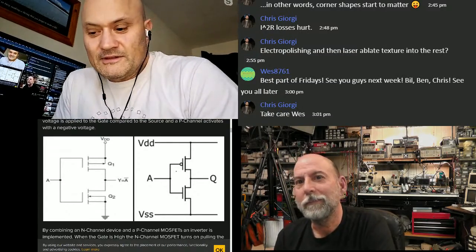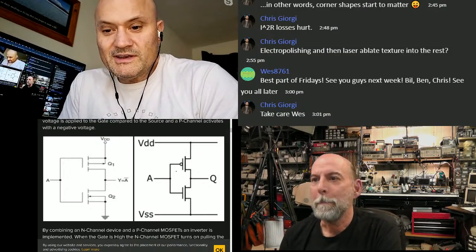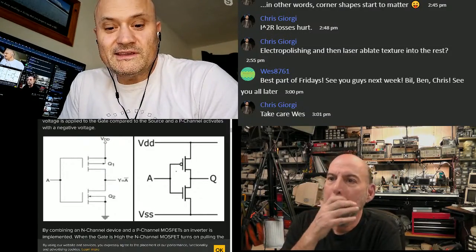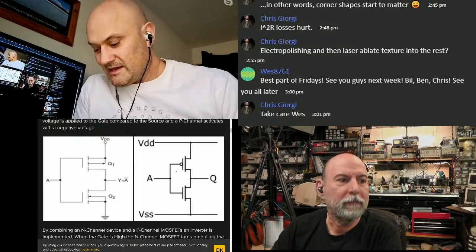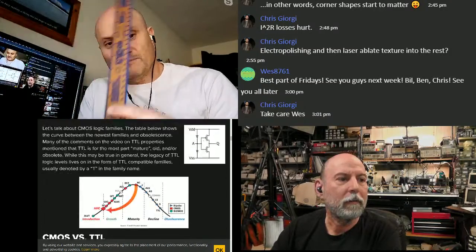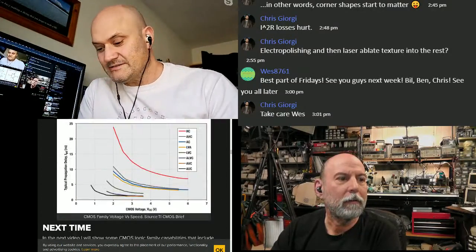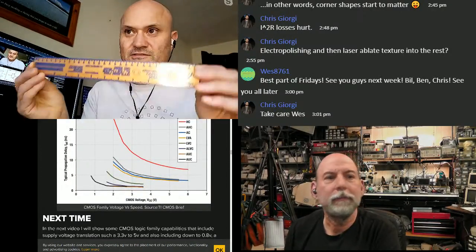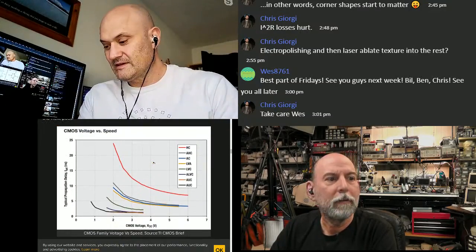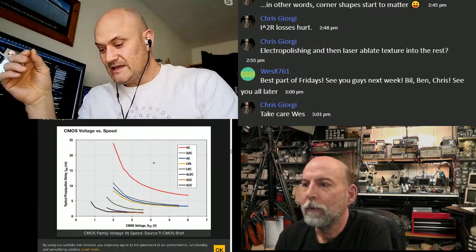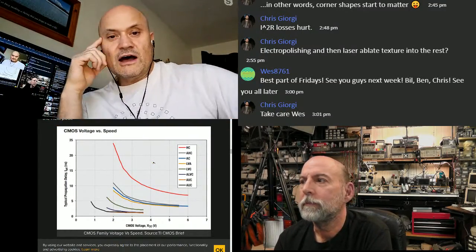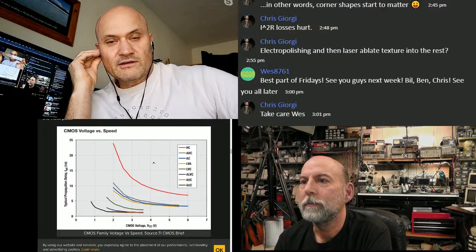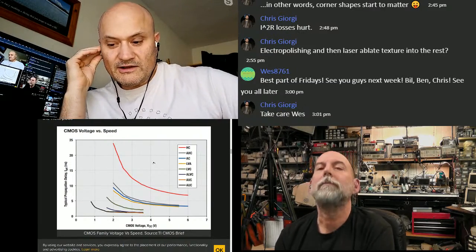So, the coupon is meant to be a small bit of PCB that, it's smaller than this ruler, but something like this, that you ask for if you're doing impedance controlled routing or any kind of RF.